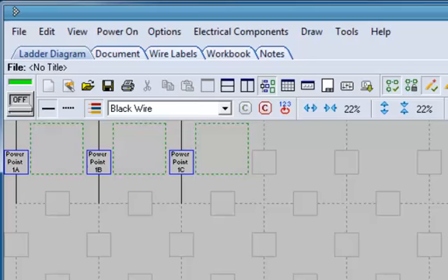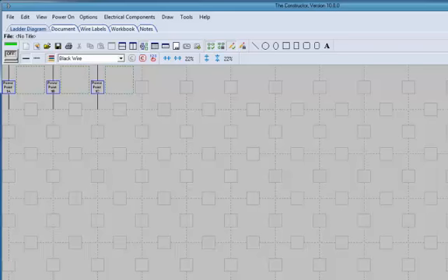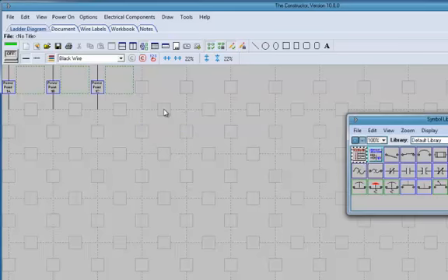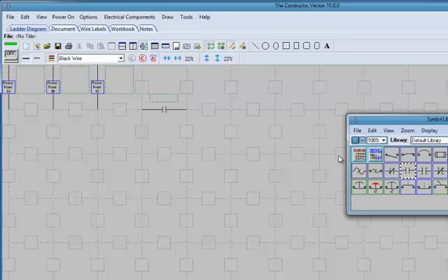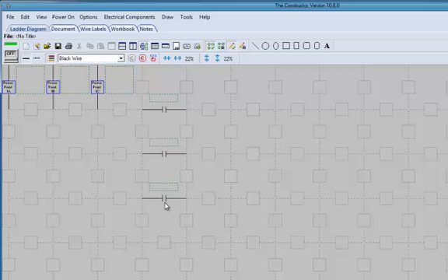In this case, we're going to make them M1. So I will begin by placing them on the drawing, right-clicking on the boxes, pulling up my toolbox, default library, clicking the normally open contact. Now I want to connect those lines to my 3-phase power. So here's my C, my B, and my A.